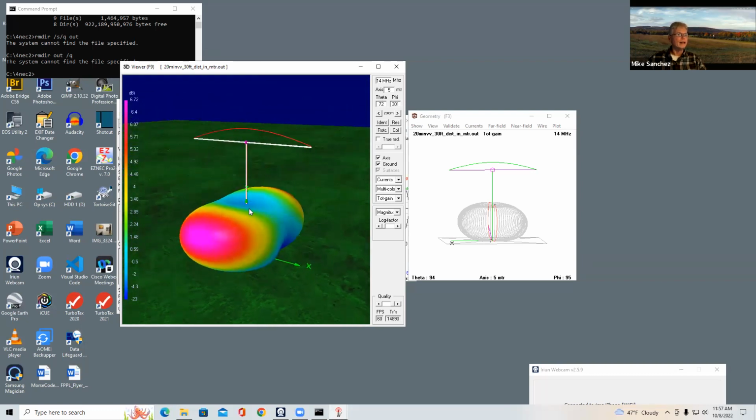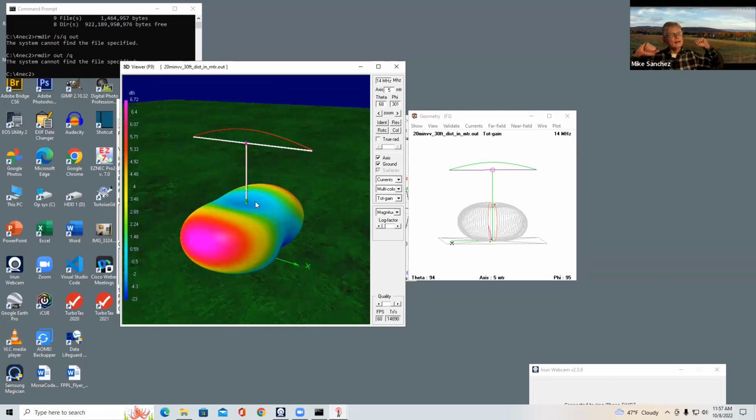But I was doing great with Pennsylvania, and I read about OCFs, and I decided I wanted to build my own 4-to-1 balun and build an OCF. So I built one over a weekend. I built the balun, ordered all the little magnetic stuff you need, built the whole thing, checked it with my impedance meter, and it actually worked. It took 200 ohms of resistance and brought it down to like 53 ohms, 52 ohms. So success there. I put wire on it and put it up, and I scanned the SWR with my meter, and it was phenomenal.